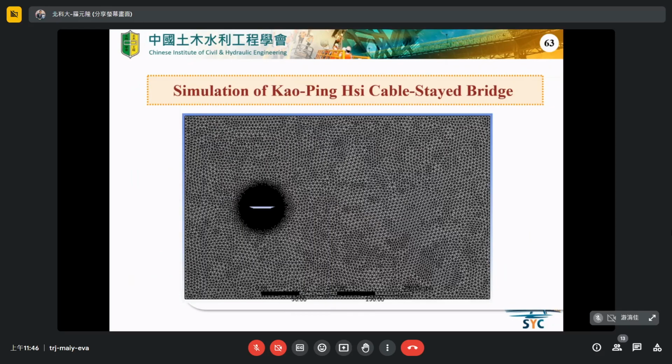We have conducted 2 wind tunnel tests. As you know, the wind tunnel test requires lots of money and lots of time. We submitted the case to DMI in Denmark, and we had to line up. At that time, aerodynamic analysis was not so popular, so all the problems related to aerodynamic stability could only be made sure by wind tunnel test. However, with current technology, we can use CFD, computational fluid dynamics, to do it.